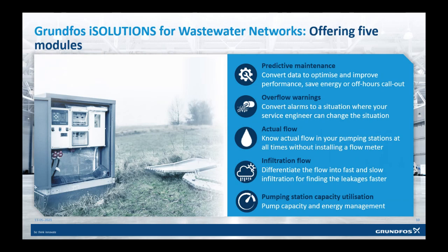It gives you overflow warnings. So it monitors the capacity of your network in a specific catchment and tells you where you might see an overflow in 8 hours, 16 hours, 24 hours, depending on some of the data inputs. It monitors actual flow. So it knows the actual flow in your pumping stations at all times without the need for installing a flow meter. And that's really important because we know that installing flow meters can be quite expensive. So we use algorithms and data inputs to calculate the flow at a pump station at any given time.